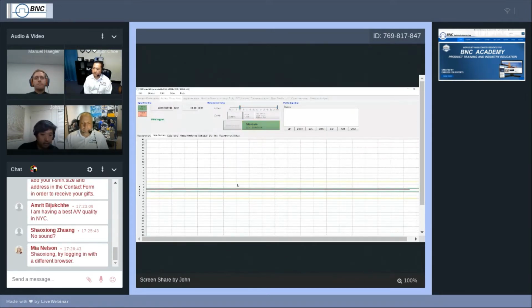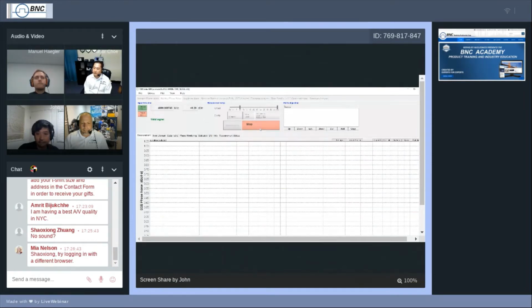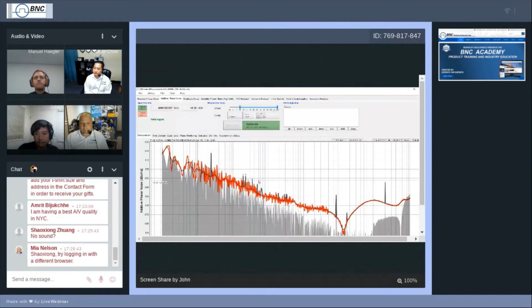As you can see, my references are already in quadrature with my DUT signal. It also shows on the GUI as the measure button turns green. From this point, you can just click measure again. This is the phase noise floor of my device.